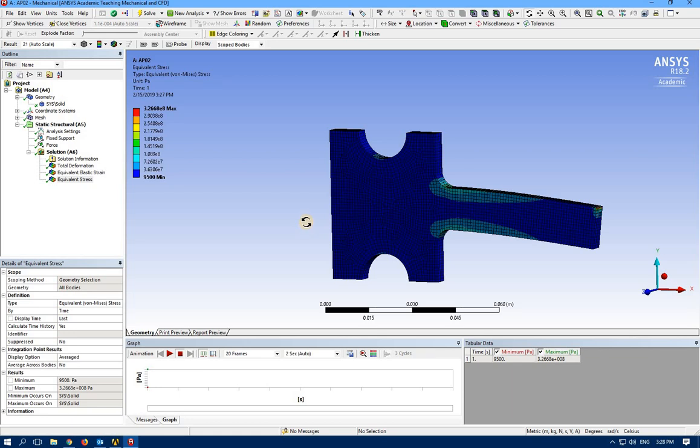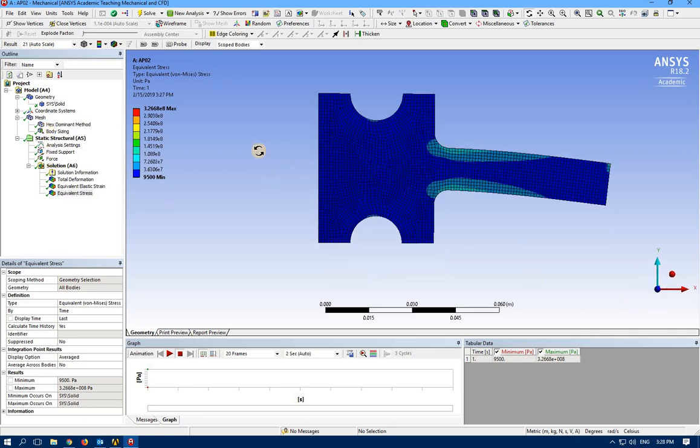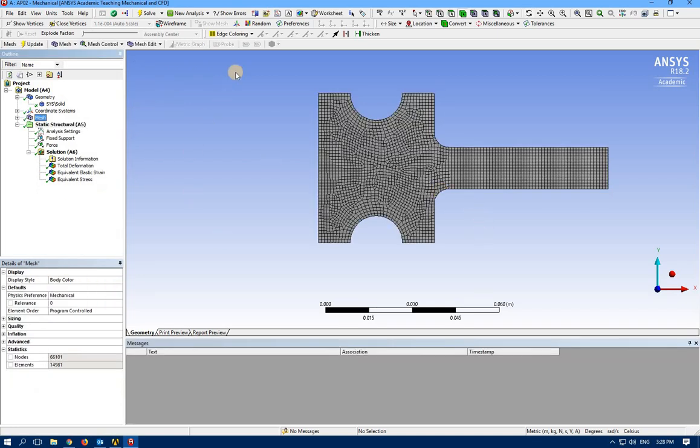If there was a conflict between these mesh commands or different options, ANSYS automatically is going to select the higher level one. Okay, what's the problem with this mesh? It's uniform for everywhere, which we don't like. We want to have concentration of mesh or finer mesh for the area we know there's a stress concentration. For the other area we can have larger mesh.